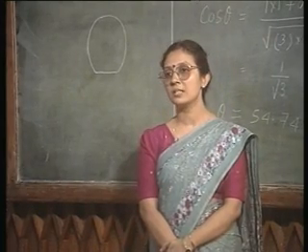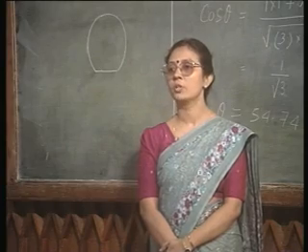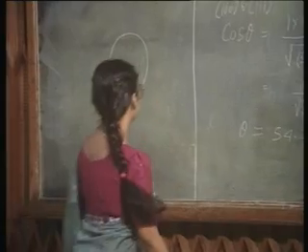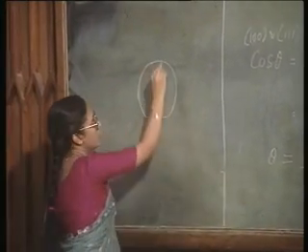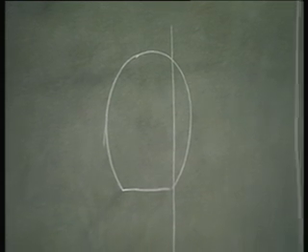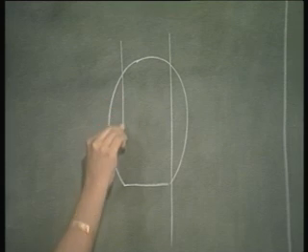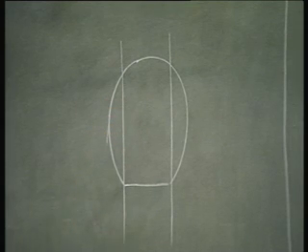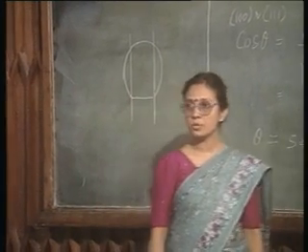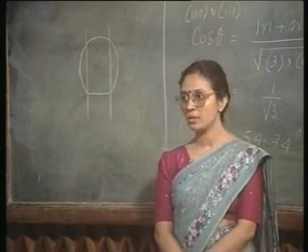This simply signifies that I am going to specify one scribe line for you. So, this flat is provided on the wafer. Your first scribe line is perpendicular to this flat. These are the first two scribe lines. Perpendicular to the flat, you can scribe.